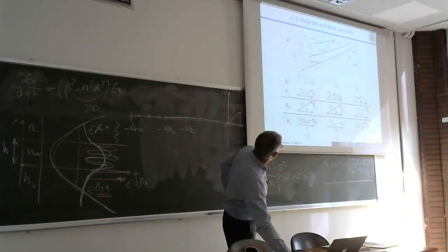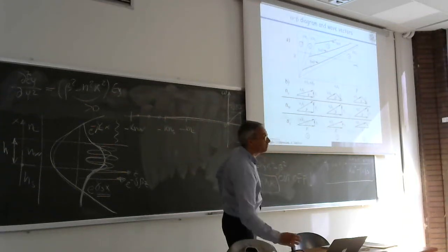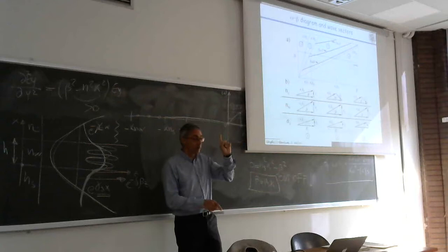In this case, we have 2, a guided wave in the cover. So here you have a total internal reflection, while here it is no more guided. So you don't have total internal reflection here, and you lose energy in the substrate. So this is a radiative mode of the substrate. And after this point, here you have radiative mode both on the substrate and on the cover.